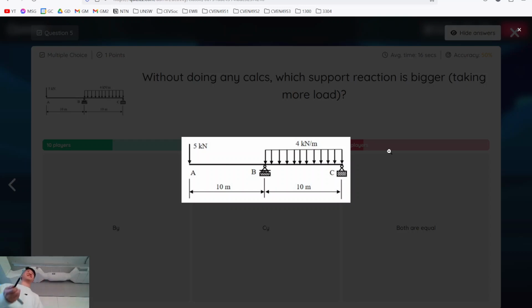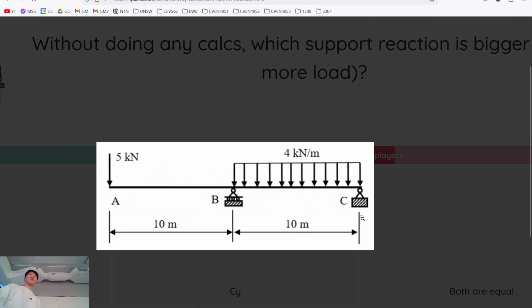So in your midterm, if you run into a situation where you calculated this and your vertical reaction at C is bigger, you messed up, basically. And you won't even know that because to get the second vertical reaction, you're going to take the sum of the forces and it's going to appear to be right because both of those forces, By and Cy, are going to equal the downwards load. It's going to appear to be right, but you did something wrong in your sum of the moments calculation, if that's the case. So just have a good intuitive understanding of how these reaction numbers will work.